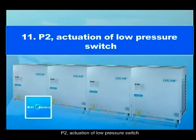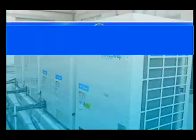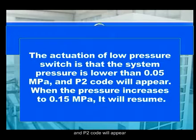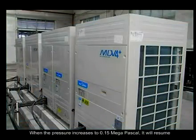P2. Actuation of low pressure switch. The actuation of the low pressure switch occurs when the system pressure is lower than 0.05 megapascal, and the P2 code will appear. When the pressure increases to 0.15 megapascal, it will resume.